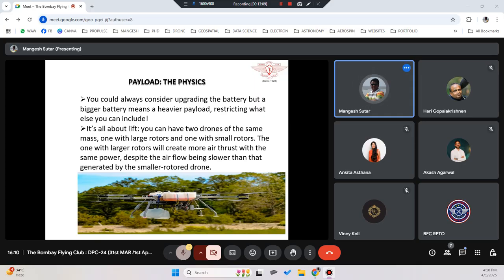There is a drone which has been developed with an extinguisher attached to it. If there is a fire at a very high altitude, you can fly those drones and trigger the extinguisher from the drone. In that scenario also, it depends upon what weight it can carry, or how that 50% ratio is managed. It's not that if it carries a 3 kg extinguisher, I think okay, I'll put a 5 or 6 kg extinguisher. No. If that particular drone is designed to carry 3 kg of extinguisher, you should put only 3 kg, not higher.